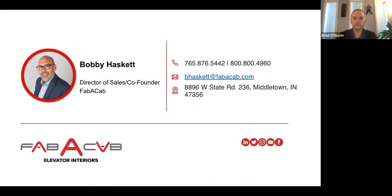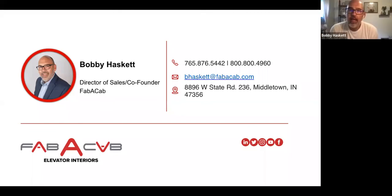We have a couple more that came in here. Matthew asks, what height do you recommend that handrails be put at for accessibility? Yes, your code's going to vary per region. I know that everybody knows that, but for most of them it's 32 inches at finished floor.